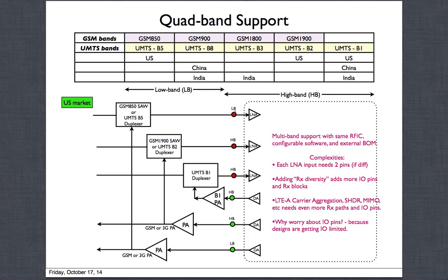You can't just make them bigger and bigger, it's expensive, it doesn't fit on the phone. So these I/O counts are becoming extremely important, and all kinds of techniques to reduce I/O counts are very, very important now, because most designs are I/O limited. The die area is limited by the number of I/Os we need and the area of these I/Os, which are basically the balls or bumps, whatever you call them, which eventually go to the package.